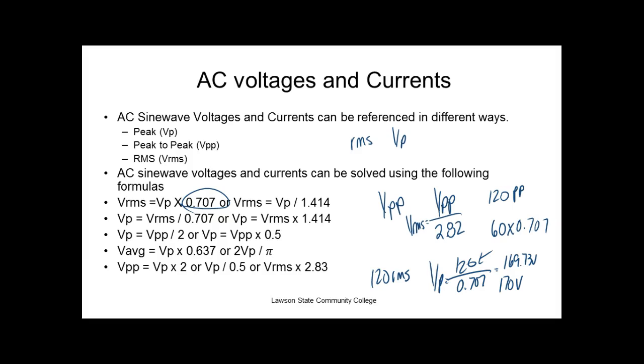Now it seems like a waste, but it's not, because we can get any voltage we want with transformers, right? You understand that? And what we can do with AC that we can't do with DC is change the voltage level with what? With a transformer. What advantage does high voltage have over low voltage?